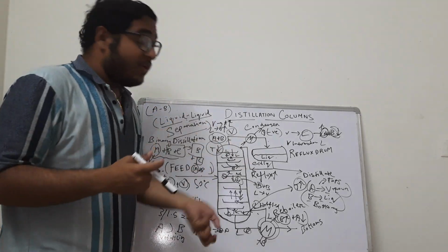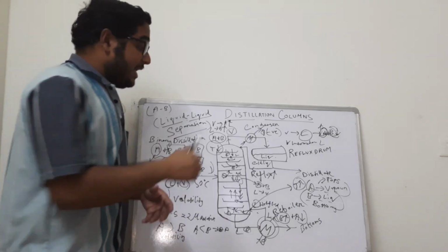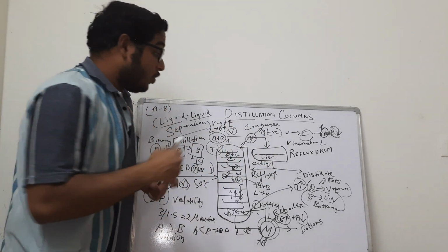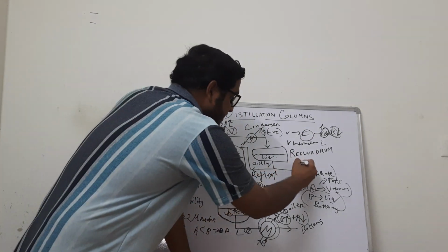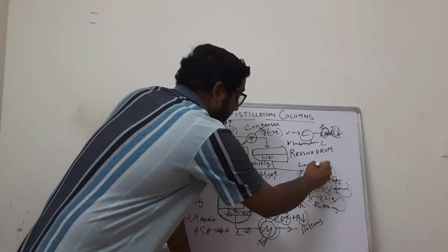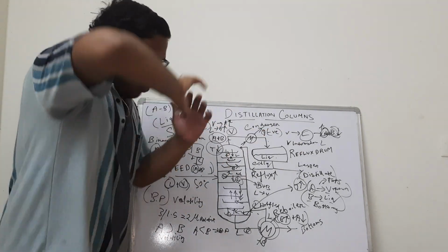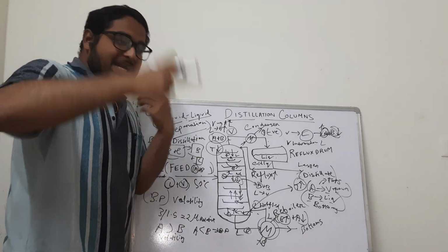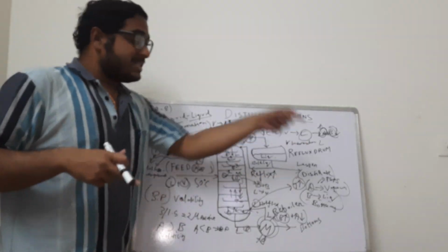So basically, reflux in any form is increasing the quality and compromising the quantity, because the more we reflux that back in the system, the lesser is the distillate. Lesser is the distillate that is collected and sent to the customer, my next customer. So with reflux, we are basically recirculating the same fluid again and again in the system, and we are not distilling it out.